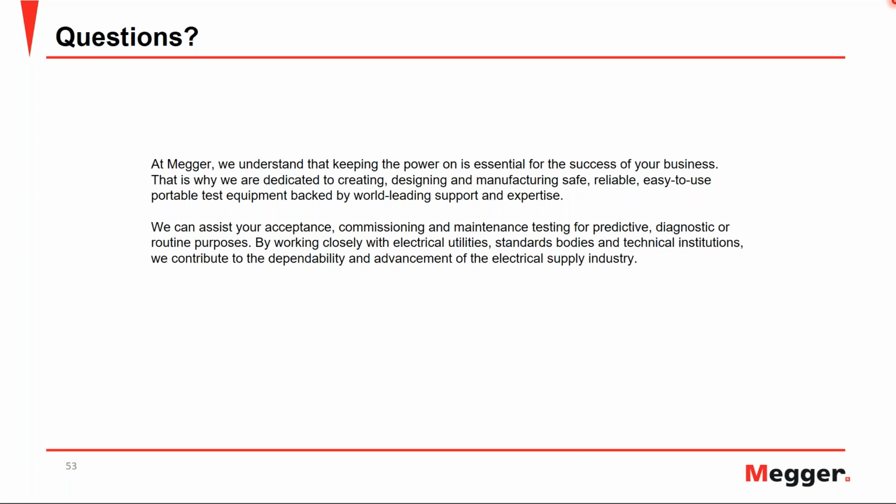And if the tan delta values are already bad, do we need to do a DFR? Well, that depends on what is being considered bad. If they're just a little above the limit established by the standard, 0.5% or something like that, then that's where power factor has a limitation: you don't know if it's really bad, or if the values are just starting to change but the changes are very small, so you have uncertainty about what to do.